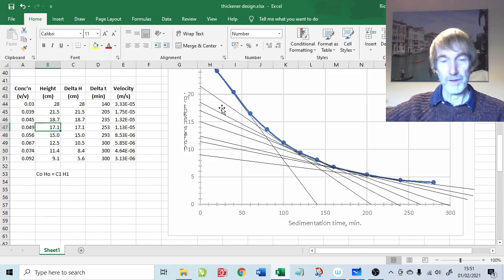So that gives us a whole array of data of settling heights for different concentrations. So we don't need to do lots and lots of batch tests, so long as we have good settling data. We can just take tangents to the settling curve, and by projection work out what the settling velocities are for all these different concentrations. And there's no need to go up to 13.8.